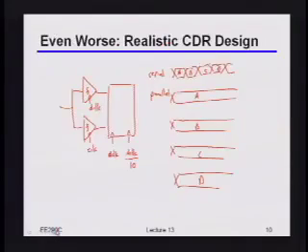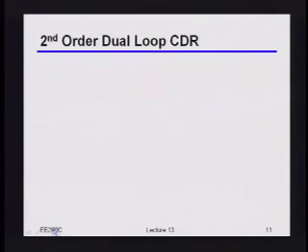So what you've basically said is that rather than just looking for phase, what I should actually do is not build a delay lock loop, but build a phase lock loop. Okay? But just to make sure this is clear, we're going to sketch this out, because remember that this phase lock loop is still separate from the real phase lock loop we're using to generate the clock in the first place. Okay? So let's draw what this looks like.